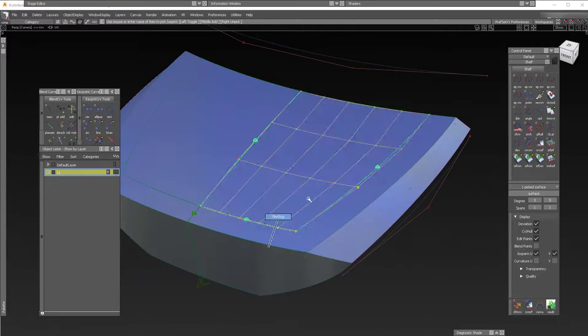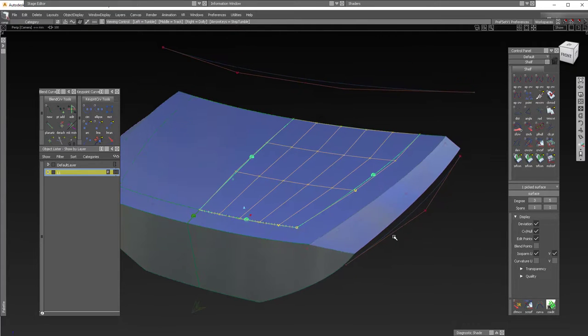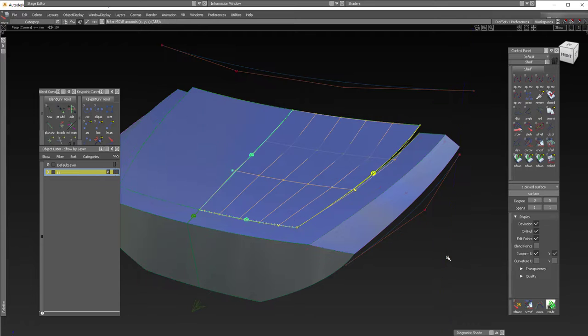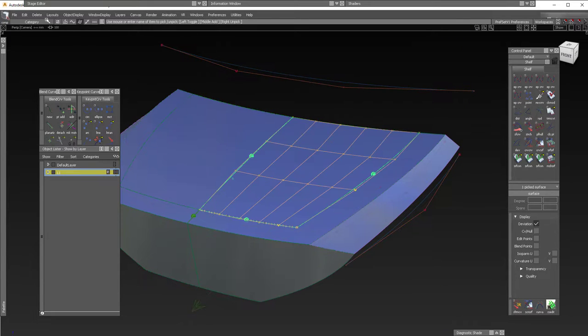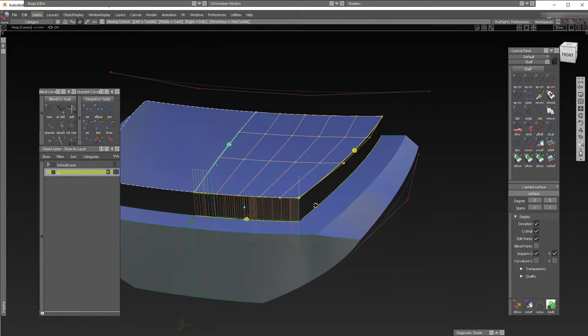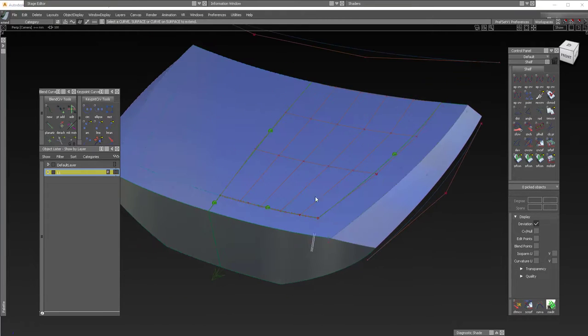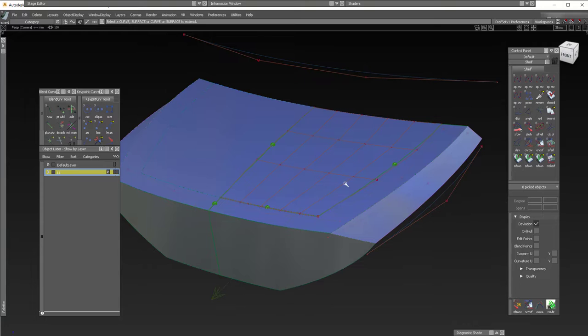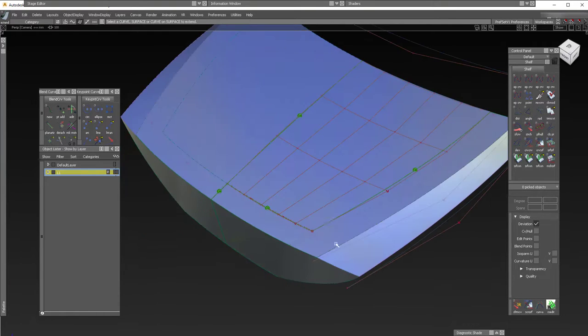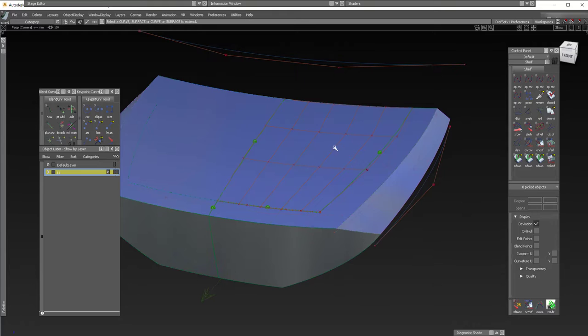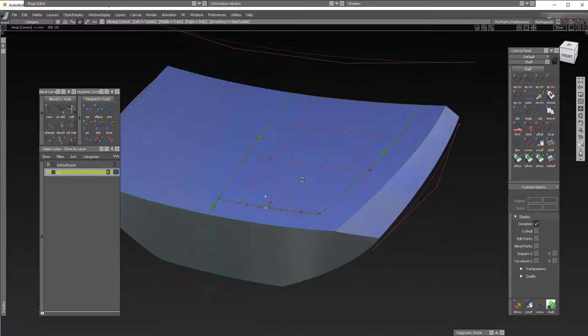Now everything's fine. So from now on I can move this part of the surface, and before doing it, I need to delete the construction history and shape these areas, like, I don't know, maybe extend back this part of this surface. It depends on your design intention. So this is how trim convert works, and from now on just have some cup of coffee, cup of tea, however you like, lay down and just watch and enjoy the rest of the video.